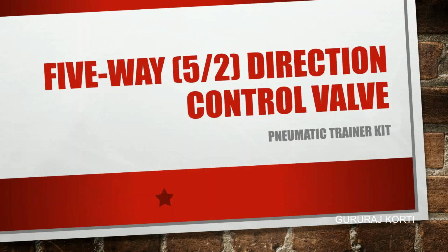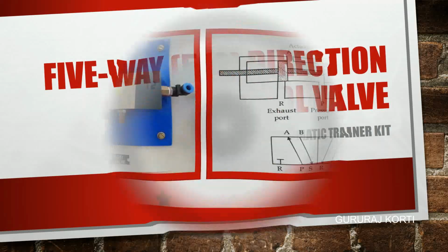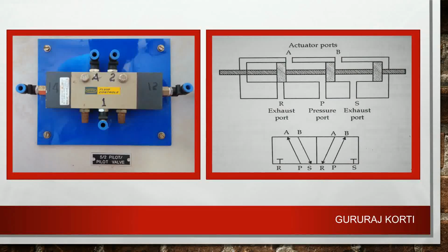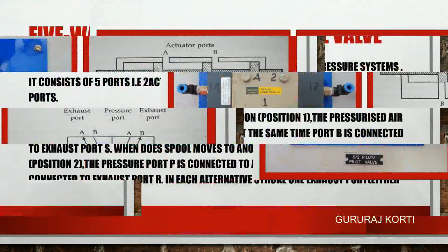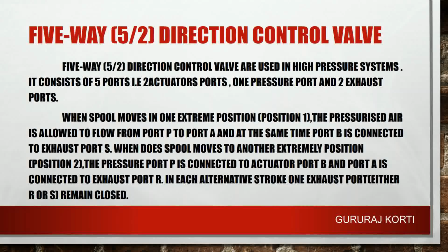Five-way, 5/2, direction control valve. Five-way, 5/2, direction control valves are used in high-pressure systems. It consists of five ports, that is, two actuator ports, one pressure port and two exhaust ports.